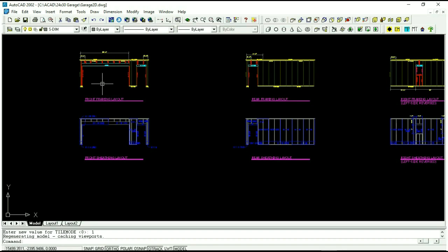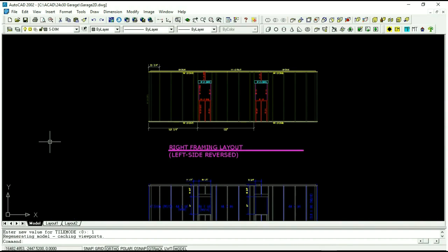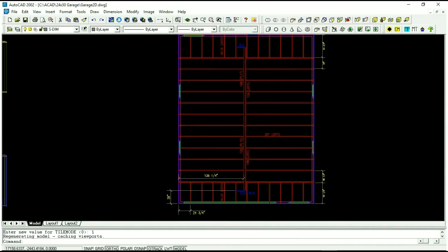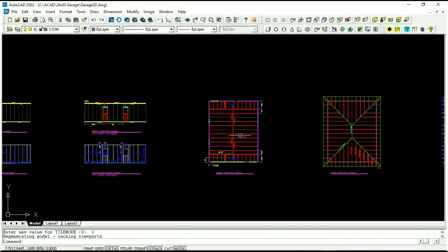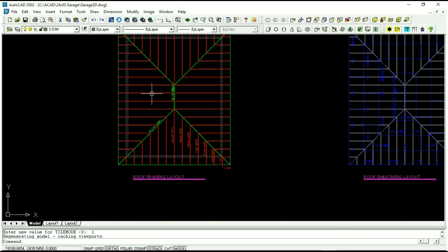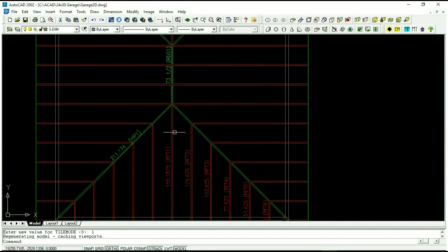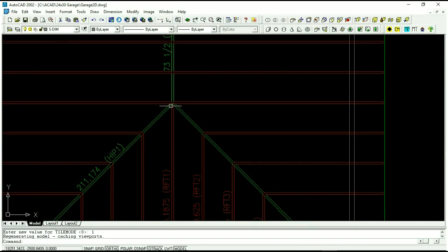So what I'm going to do is build the front wall first, then you build the rear wall, and you do them in 3D, but they're on a 2D plane basically. Then you do the right and left walls, and then you do the roof joists because they're all in the same plane. Then I'll do the rafter framing, and even though each face is in a different plane, these are pretty easy to do because you can mirror and rotate things, and they keep their planes pretty well. So when you rotate this group of rafters over here about the center of this ridge, it'll make these rafters right here, and they're all in the same plane. It rotates the plane too and keeps everything.